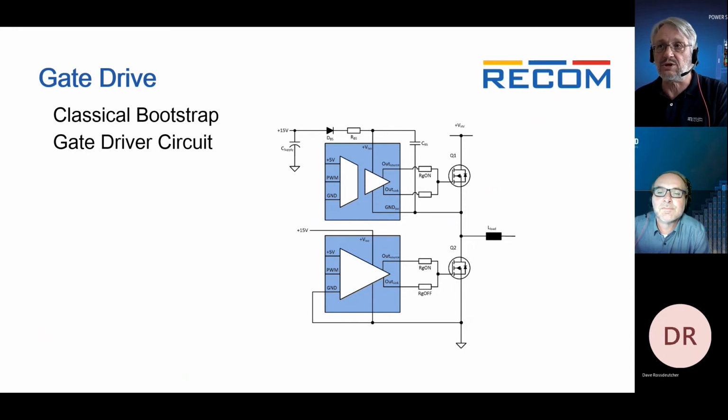But when you get to higher frequency, there are a lot of problems with this kind of design because it's not very stable, especially during the first few pulses. Wide bandgap transistors can switch so fast that even the first pulse or the second pulse, if it's not stable, can cause you serious problems.